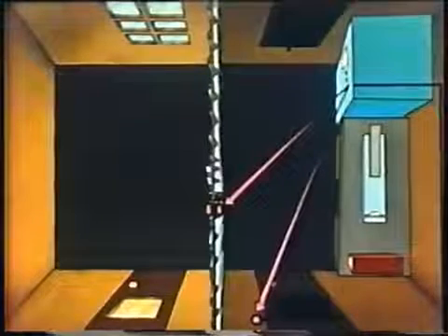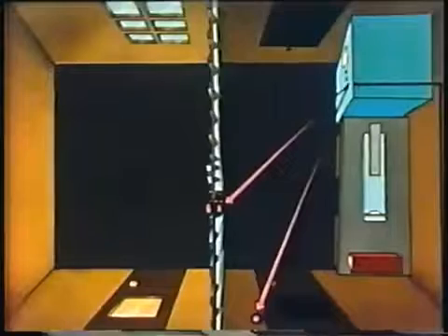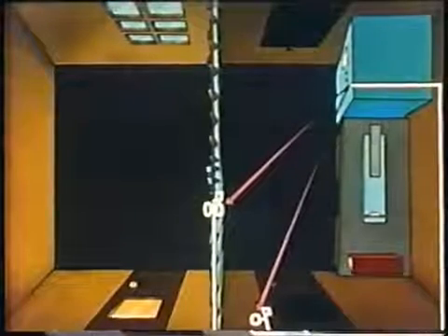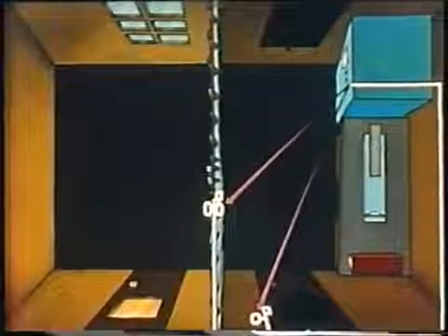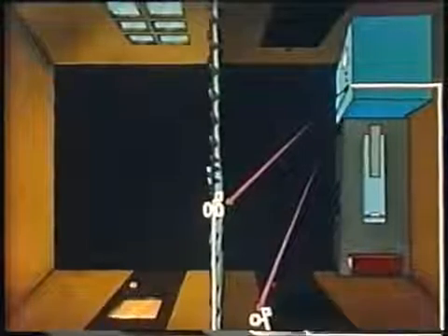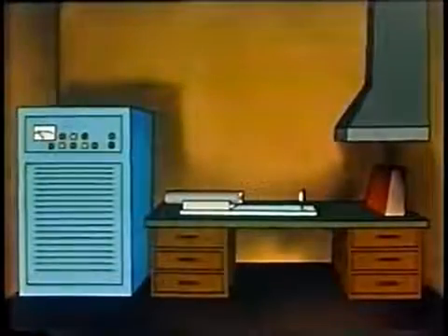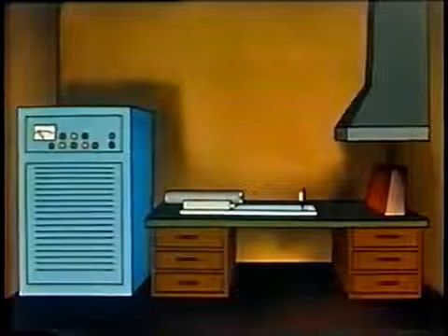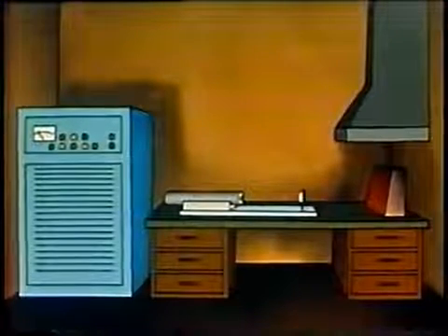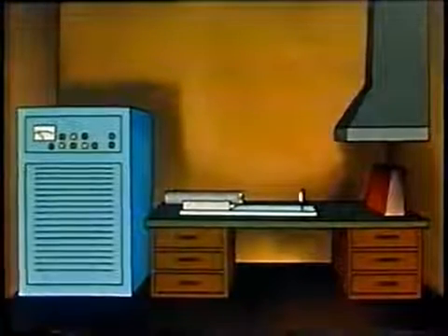The interlocks are connected to the power supply. When the power supply is turned on, the interlock switches lock the doors so that no one can enter during laser operation except in emergencies. The lock should not prevent quick exit from the room. Exhaust ducting should be installed over the target area to carry off toxic gases. The laser should be positioned well below normal eye level.